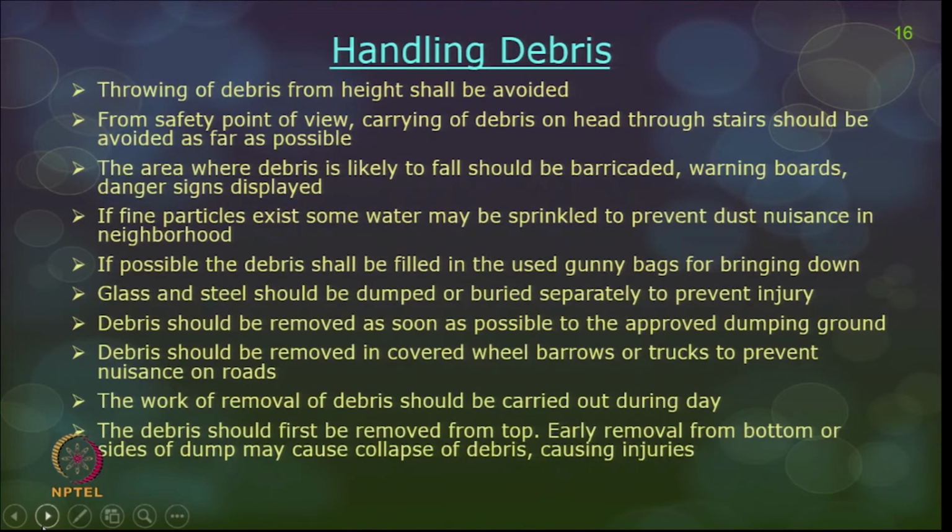Handling debris and throwing of debris from a certain height are generally avoided from a safety point of view. Carrying of debris on the head using a mortar pan or any other substances through stairs should be avoided as far as possible, because it can cause environmental pollution or it can fall and cause a slip or a trip hazard.